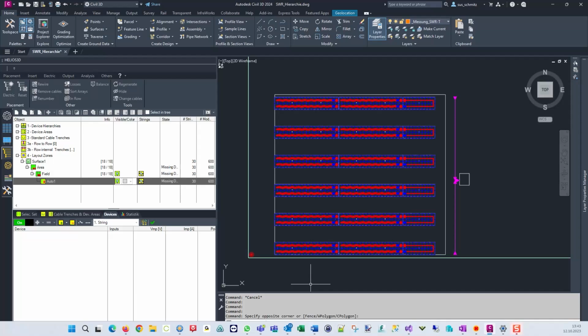The next step is to switch to the hierarchy level of inverters to add our own inverters. The two plus and minus buttons on the left side add or remove existing inverters to or from the list. That could be used to reassign strings between different inverters, but here we still need to add the first inverter. The corresponding button offers the list of inverters that have been added to the device hierarchy.